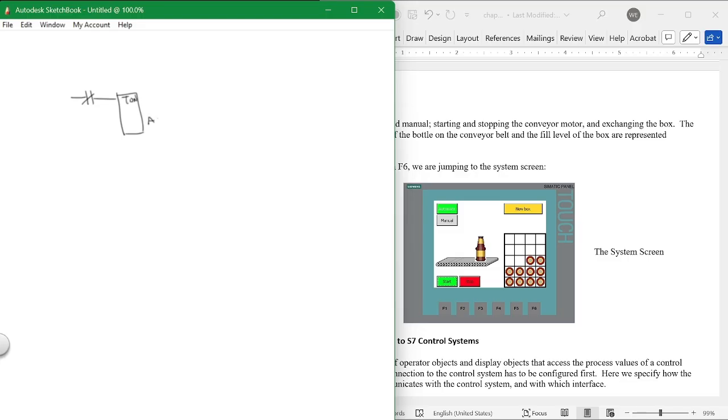And the accumulated value is what you use to move the bottle from the low position to the high position. As the number gets bigger, you tie the number and the timer, the accumulated value, to the movement of the bottle across the conveyor. And it works.